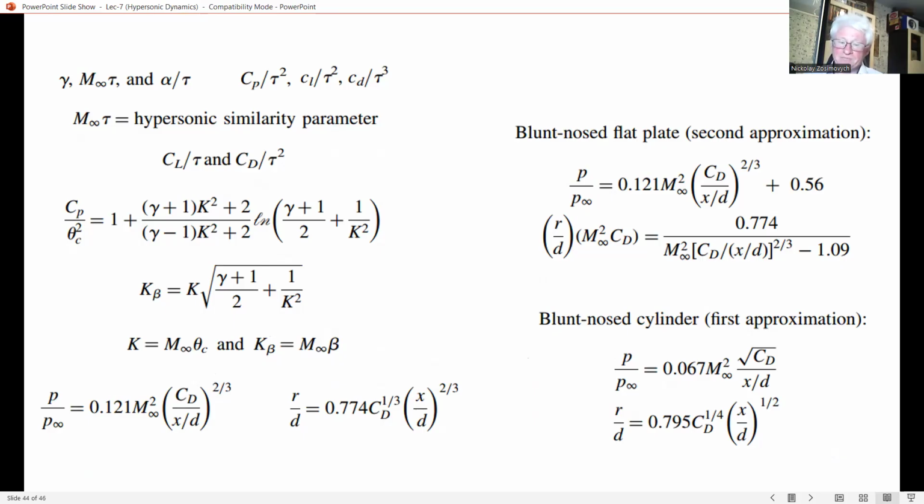A corollary to this principle is blast wave theory, which allows self-similar solutions to the unsteady flow field generated by an instantaneous release of energy along a line or plane, and to be carried over the steady flow downstream of the nose of a hypersonic blunt-nosed slender body. The results we can see here.